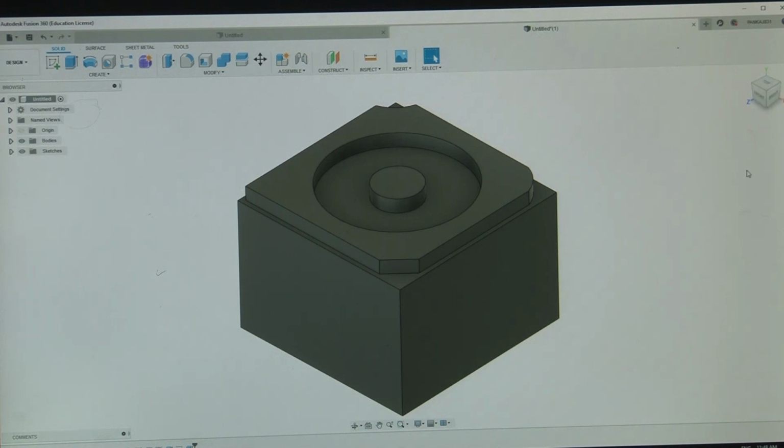Once the code is made, that is the entire program that I have shown you that we can make manually, the same program will be made here for the CNC milling of this kind of part. That can be interfaced with the actual machine, and in the machine the relative movement between the tool and the workpiece will be executed according to the code generated here by the Fusion program, and the part finally will be manufactured.